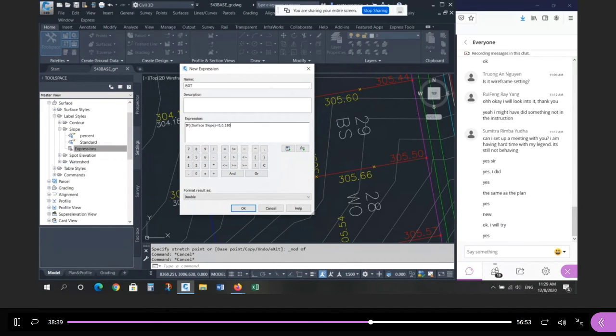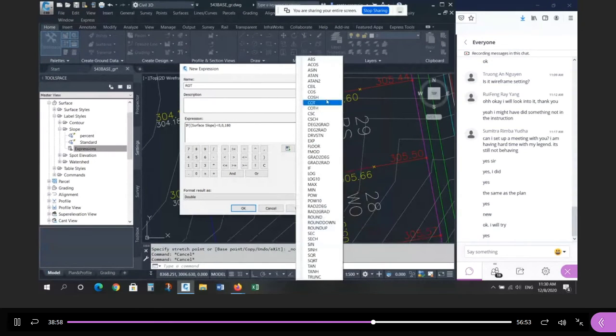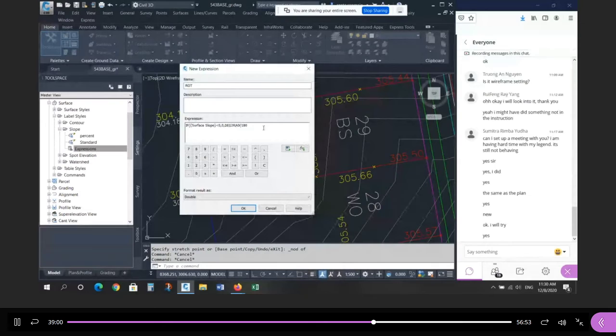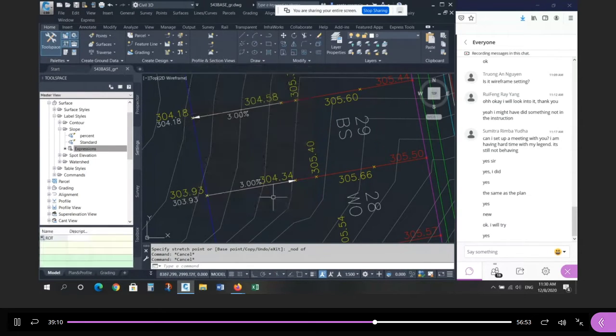In the computer, when you type in a rotation angle, 180 it thinks is radians. You have to convert it to degrees. So it needs it in radians, and the function is degrees to radians. Then it'll convert the 180 degrees to radians, and then we need a close bracket. So that's a logic statement. Say OK. Now watch what happens to this when I swap it out.